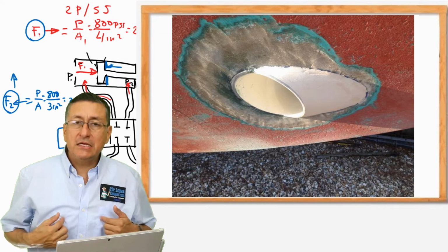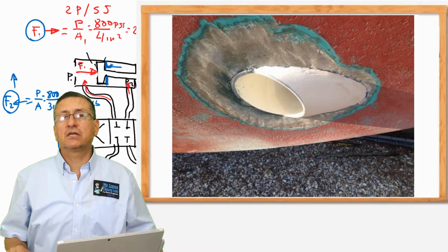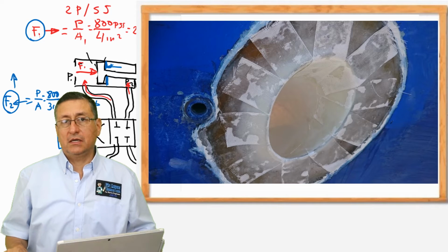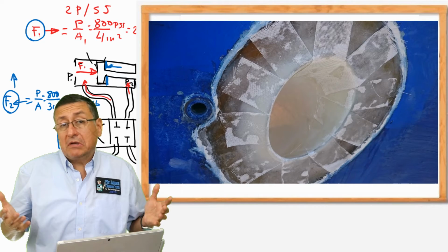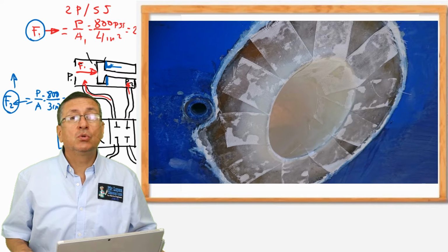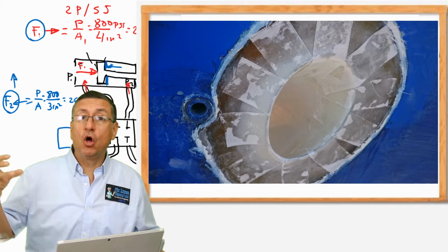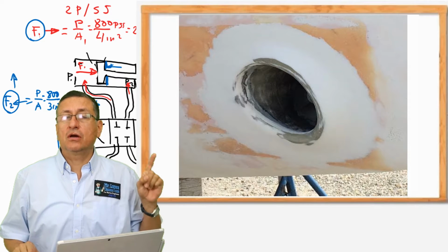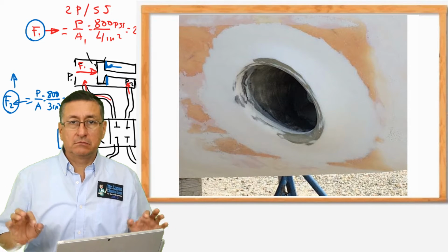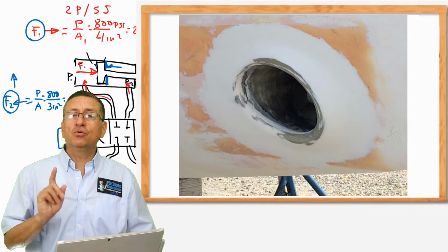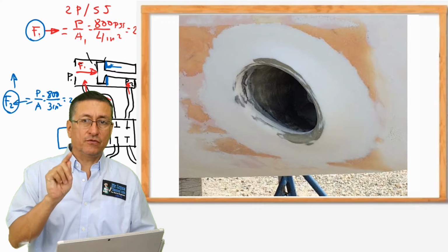Normally, when I install bow thrusters and stern thrusters, I use a contractor specialized in fiberglass, because I don't have enough experience to perforate the hole, install a tunnel and laminate. The lamination in that area is critical. If you are not an expert in fiberglass, use a contractor for the installation of the tunnel.